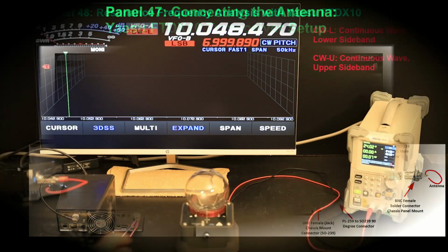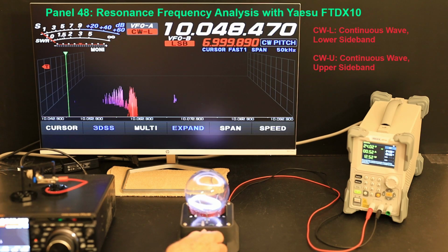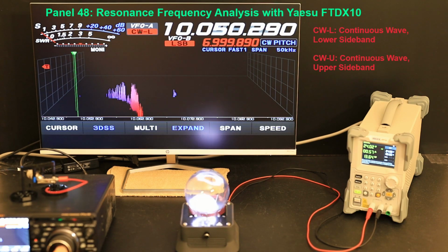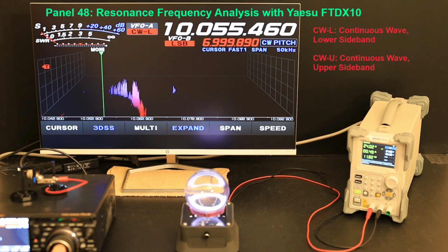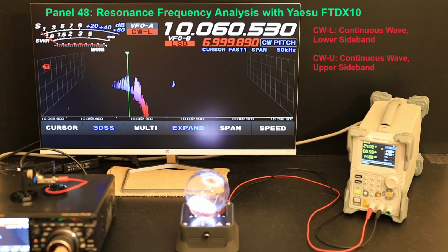Using the Yaesu FTDX10 transceiver's 3D spectrum screen, I analyzed the resonance frequency of the ModeRock oscillator to identify harmonics and multiple resonant frequencies. The transceiver offers wireless monitoring, preferred over an oscilloscope for its detailed spectral analysis, high sensitivity, and safe operation, features that are invaluable for coil design and plasma experiments.